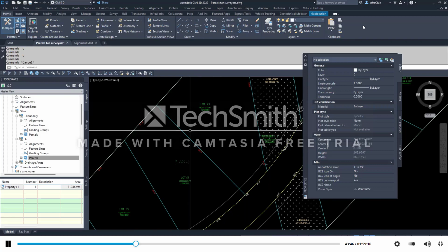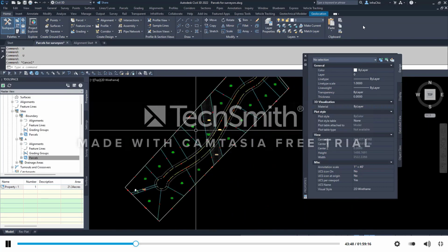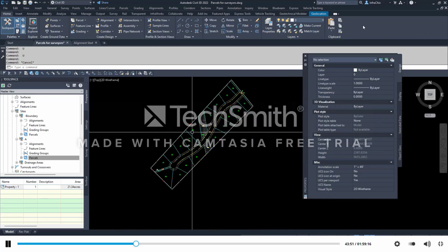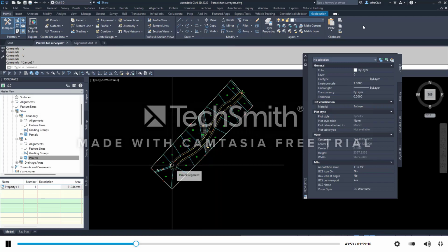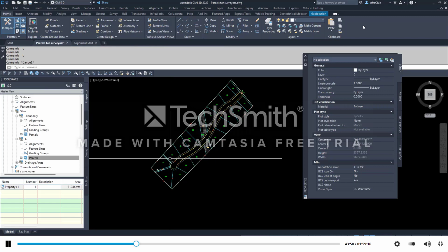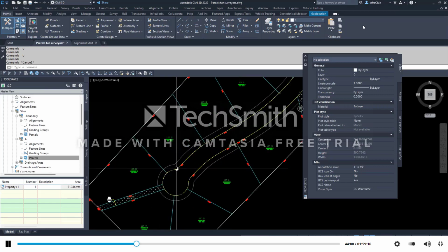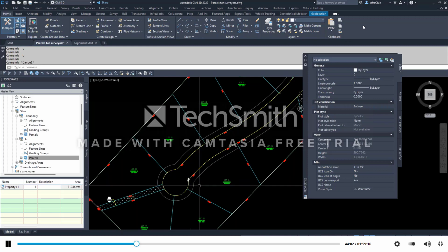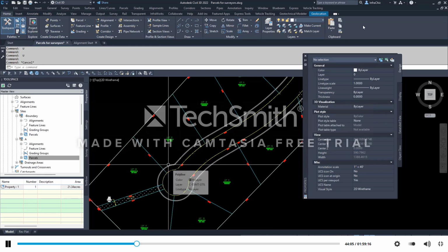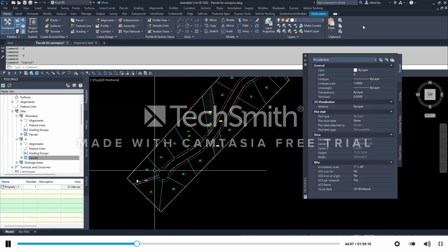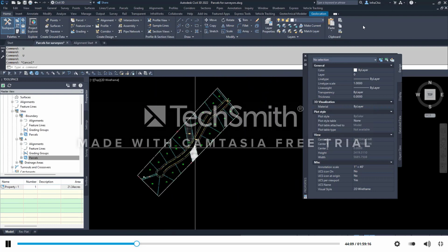Now, on this property, I'm going to let you know right up front, number one, I can only have 15 lots because according to Kaufman County, when you have a road with a cul-de-sac, it's only allowed to have 15 lots on the cul-de-sac. And I asked them about this. Doesn't the cul-de-sac mean from the start of the curb return to the end of the curb return of the cul-de-sac, no more than 15 lots around said cul-de-sac? The answer to that was no. No, that means the entire road. Okay, so that means if I broke this road up, right, and I put a crossing T in here, then it would be from that crossing T point to that cul-de-sac. That's where they would count my lots to 15.